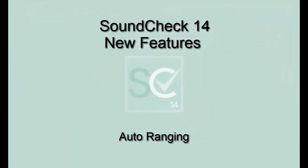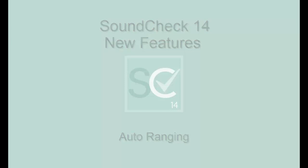The ability to read and set preamp gain in Listen hardware has allowed the creation of a new auto-ranging feature. As part of an acquisition step, auto-ranging looks at the maximum level coming into the audio interface and determines whether or not it can optimize the signal-to-noise ratio of the measurement by increasing the preamp gain. If so, the gain is modified and the acquisition is repeated. Auto-ranging will also decrease the preamp gain in the event that the interface input is saturated.